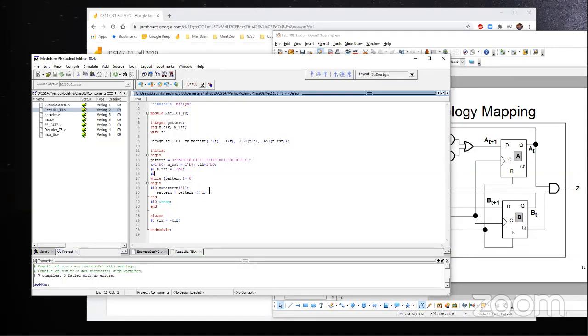That means within the first 2 nanoseconds, my machine is reset and these terminals become 0, 0. Then I wait for 4 nanoseconds, and in a while loop, I am extracting the bit pattern from the MSB side. So I set the X register value with the MSB of this pattern integer, which is holding an integer, and shift that pattern right by 1 bit.